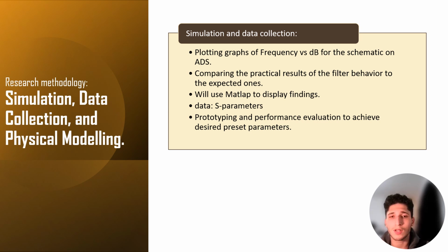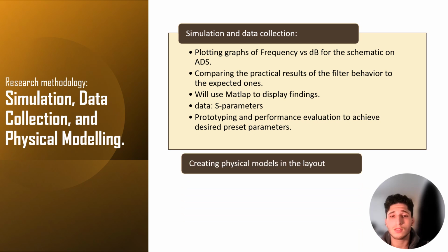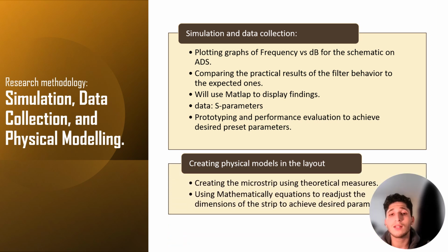and calculated one. In addition to that, in the multipole filters, when we start simulating the microstrip, we will use the graph to ensure an acceptable practical coupling, and we will be doing that by using formulas and keep adjusting the distance between the poles until it meets the theoretical calculated one with an acceptable error of plus or minus 1%. We will be displaying the final results using MATLAB software to ensure clarity.